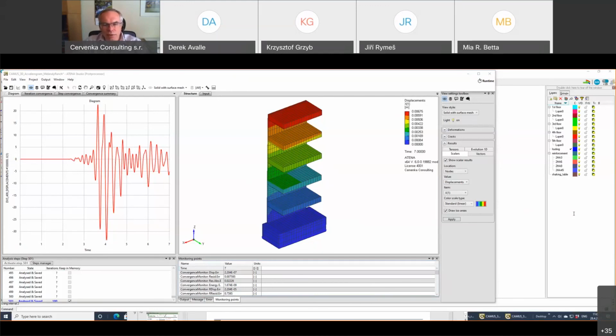So after this interval with the seismic load, you can add another interval where you can modify, add some elements, and then make some additional loading to see the effect of these other structural elements which were added to the structure, which may simulate the effect of the strengthening.